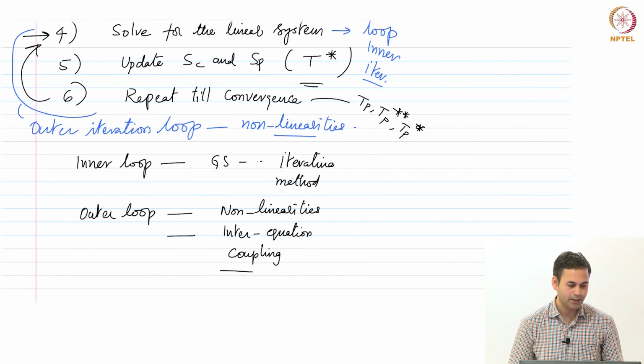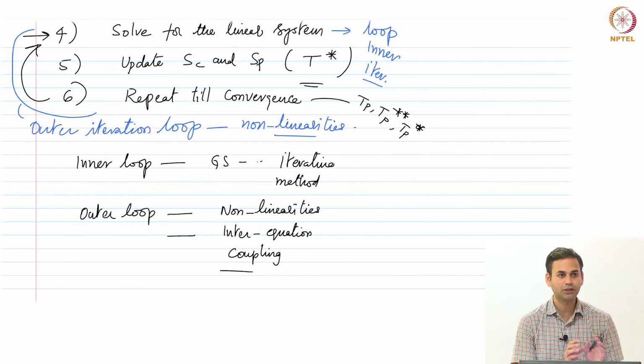Okay, then we have finished these parts. The next concept is basically going back to the diffusion equation. Up till now we have applied it to Cartesian meshes. Now, the same methodology that we have developed can be applied to other orthogonal coordinate systems. For example, if you have polar coordinates or axisymmetric problems in 2D, the same methodology can be extended to all other orthogonal coordinate systems.